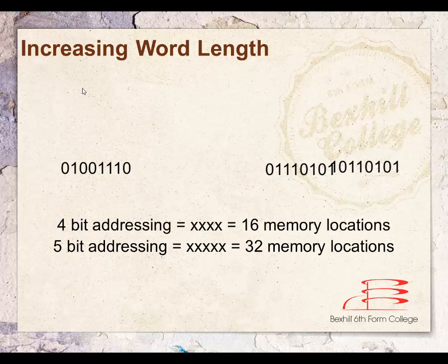If I have a 16-bit word length, then I can only execute the instruction and half of this number. I then have to wait for the cycle of the clock to allow myself to send the second part before I can complete the operation. So if I could increase the word length by getting a new processor that can handle other word lengths, I can then execute the whole 24 bits. And if I can execute it as one single cycle, I've just made my processor a hell of a lot faster.